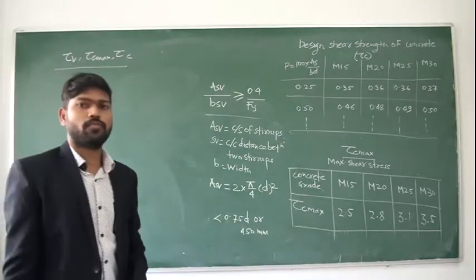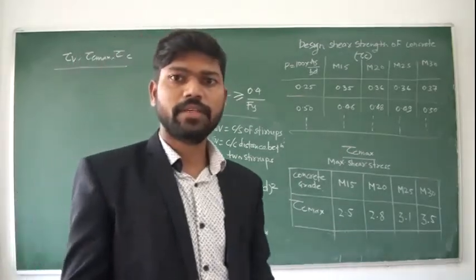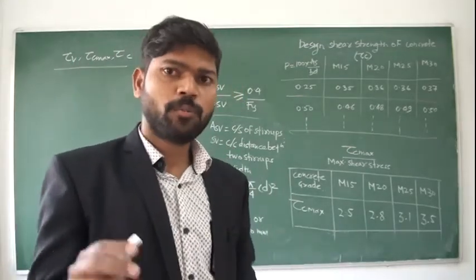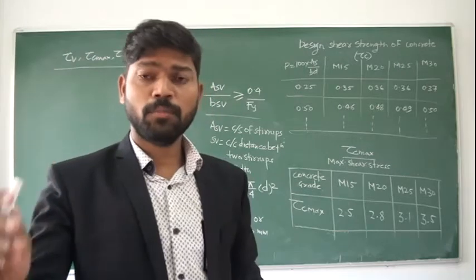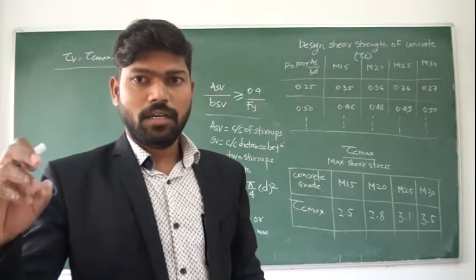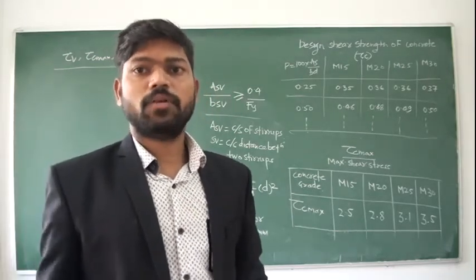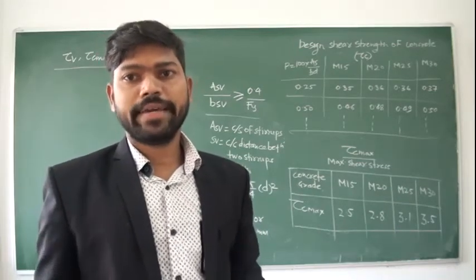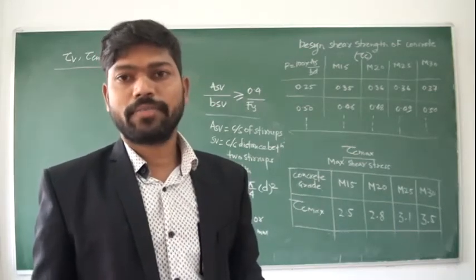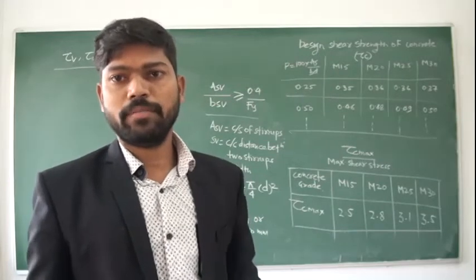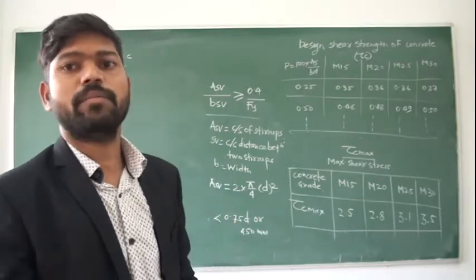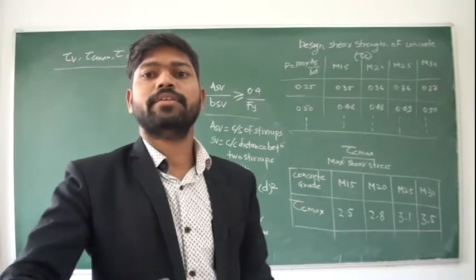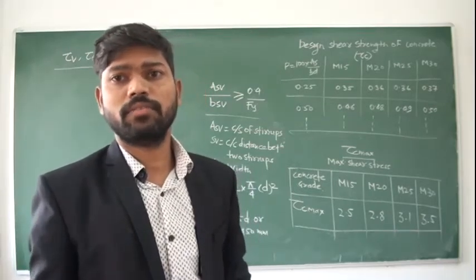They will give you the shear force in the beam, say 40 kilonewton. The reinforcement provided is 4 bars of 20 mm diameter, M20 grade concrete, Fe415 grade steel. The depth of beam is 600 mm and the width of beam is 230 mm. Design the shear reinforcement.